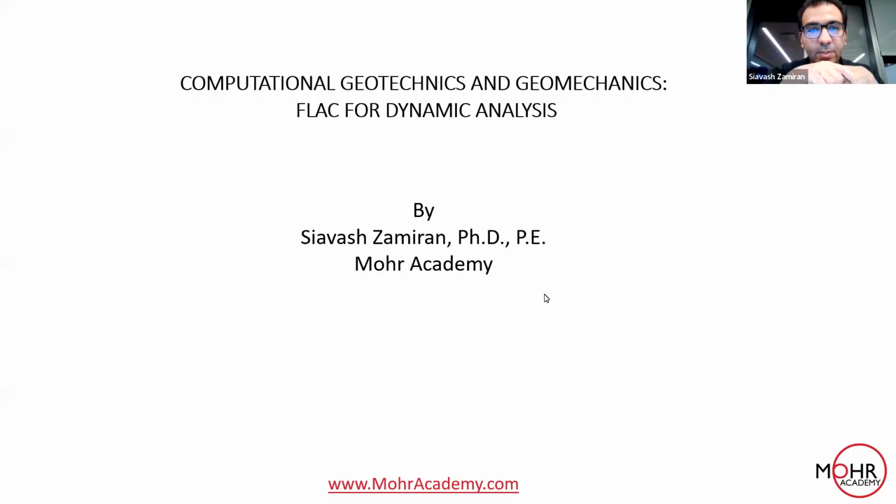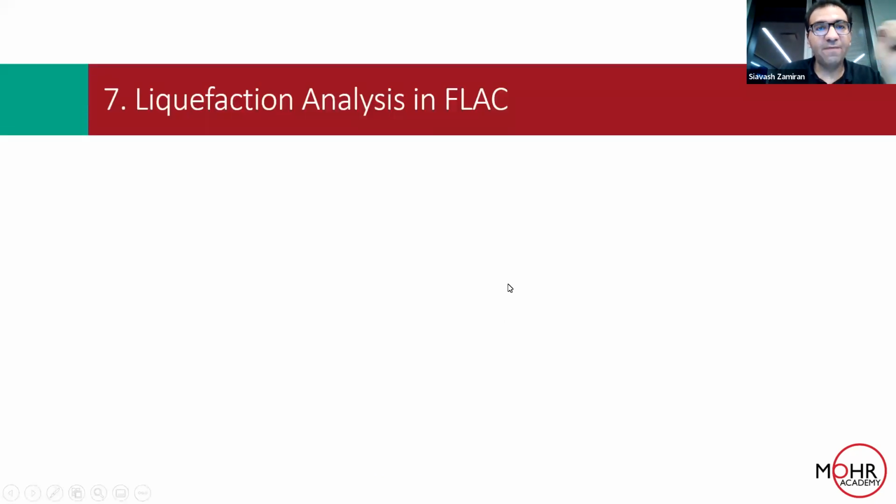So we are going to start our next section, section 7, liquefaction analysis in FLAC. Liquefaction analysis is a type of dynamic analysis procedure in which we also consider flow and pore water pressure inside the soil during the earthquake excitation.